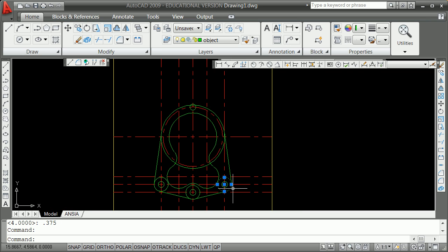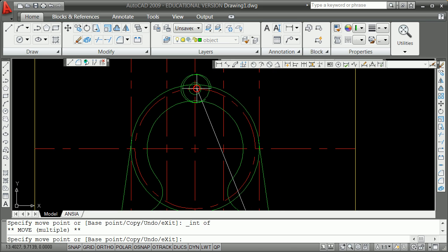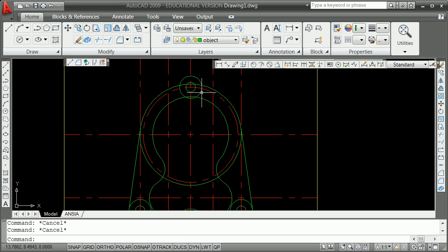So in all reality, you probably could have done left click, spacebar, C for copy, shift right click, intersection right there. Now you're going to copy that a few times around. Now it looks a little better.